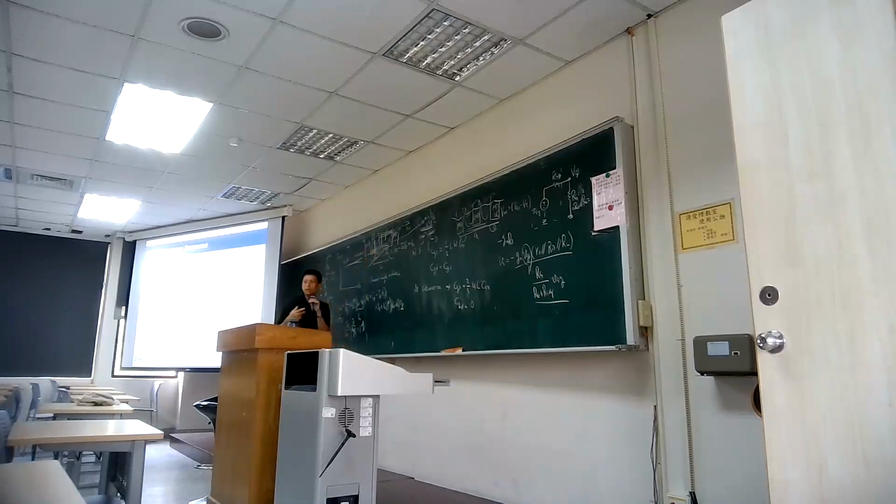The overlap here is still outside, so there will be some overlap capacitance. If you are able to replace the oxide here with a low-K material, that is still a good thing, because this overlap oxide will not impact your current.